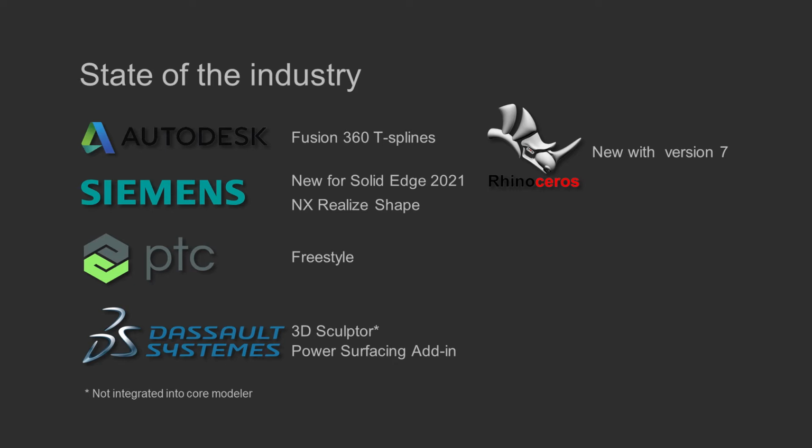But the fatal flaw in that is that not having the sub-D modeler alongside in the tree with the solid and surface modeling features, it's going to make it very difficult to get your shapes done, because I've experienced that there's a lot of back and forth between the traditional modeling tools, surface modeling tools, and the sub-D feature or features. And I think that becomes apparent with what I'm going to show you, where I use some reference surfaces and some primary surfaces before I even start the sub-D surface. And I'm using those as kind of starter surfaces and also as helper surfaces.